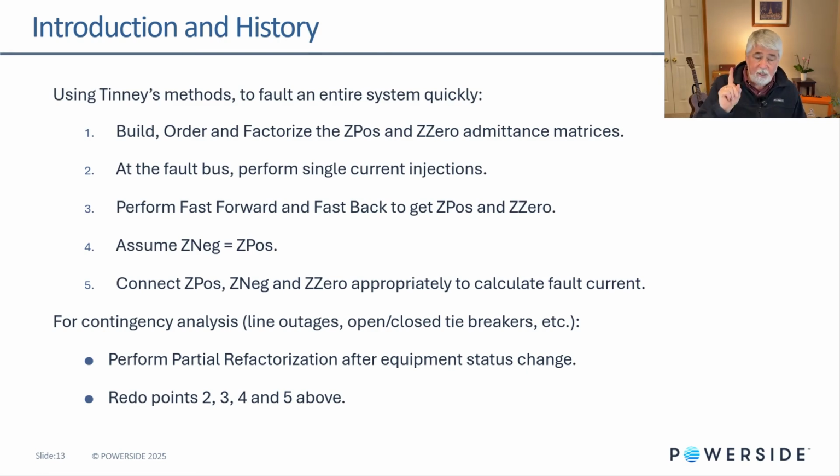And by the way, just of interest, the ordering method. If you leave out optimal ordering and you have a large network, 5, 10, 15,000 buses, you can find your computation time exponentially increasing. I did this one time. I had a 13,000 bus system, and when I left out optimal ordering, this was 15 years ago, computers were a little bit slower at that time, a power flow solution would take place in about 5 seconds.